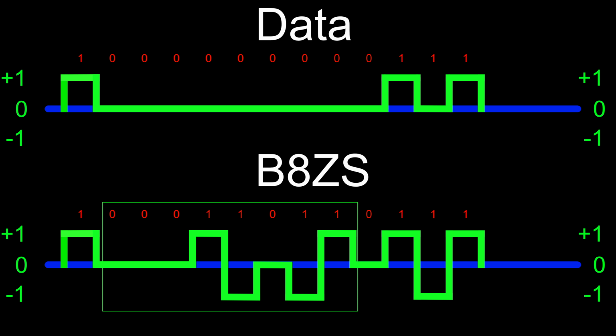Because it contained a violation of the normal line coding rules, it would never be triggered by the bit stream accidentally, and thus allowed for the full use of all 8 bits for data. By pre-formatting this structure, it was possible to include opposing bits to keep the baseline from migrating. That's why you see a +1 before the 2 -1s in a row that are the polarity error, followed by